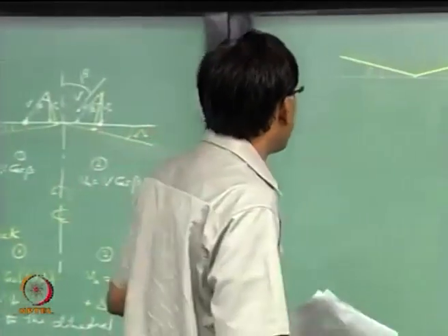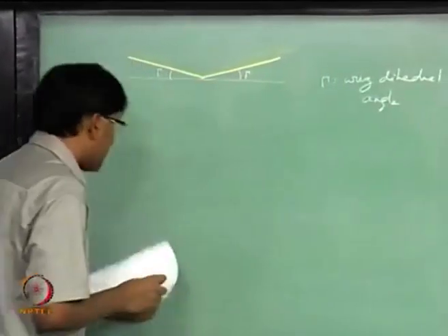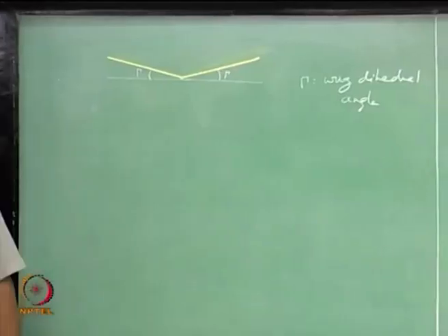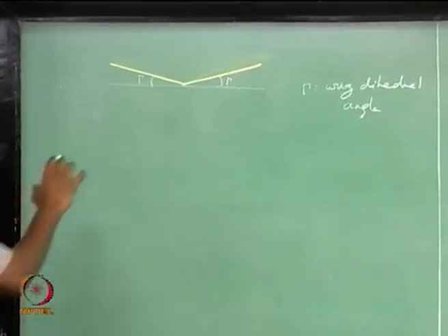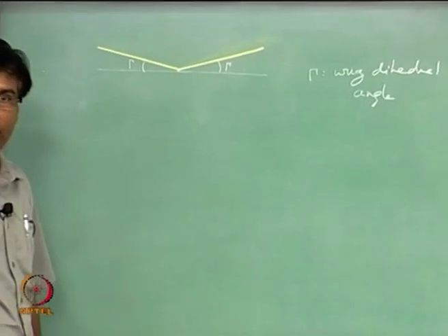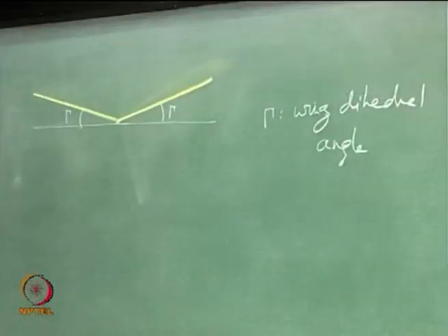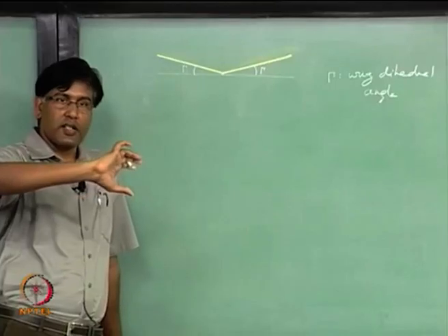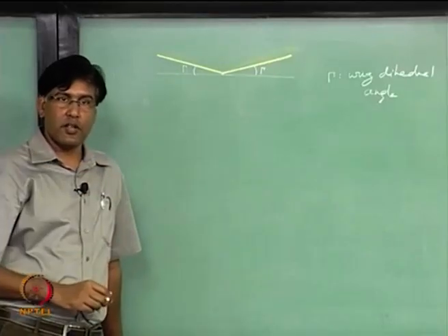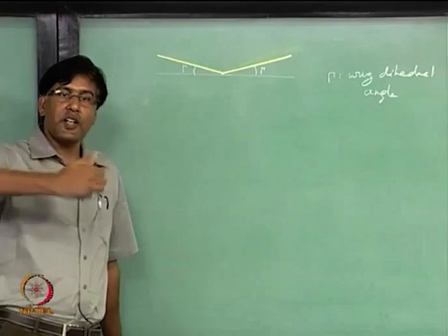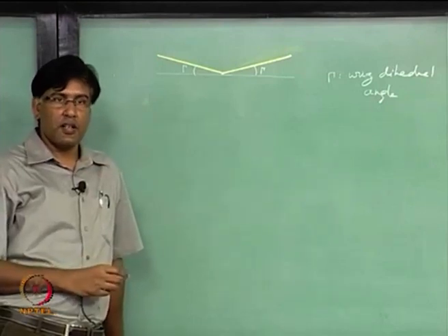So, let us see what happens when this plane is rotated, right. There is a roll upset which rotates the airplane. This rotation is a positive rotation, right, and that is what is going to give me a positive side slip, right.